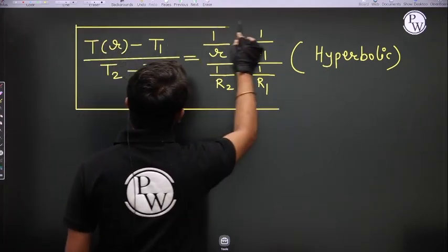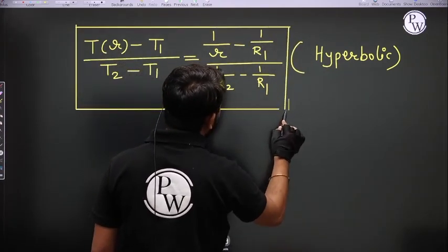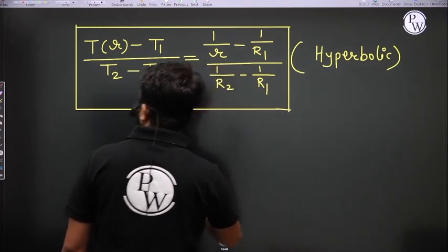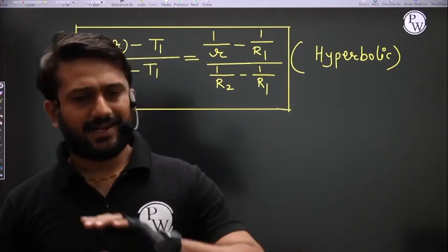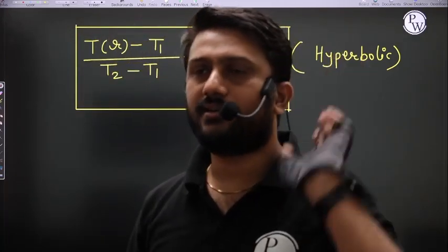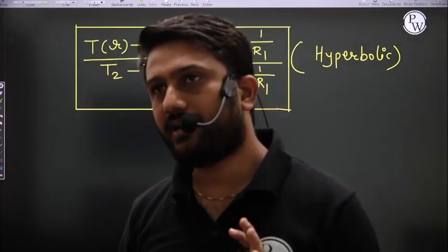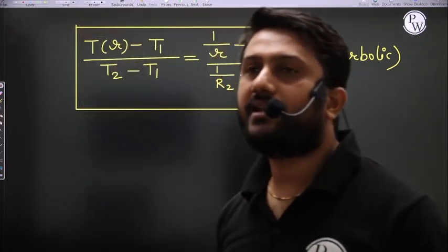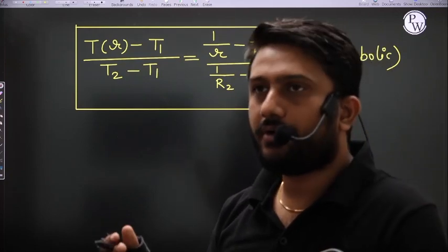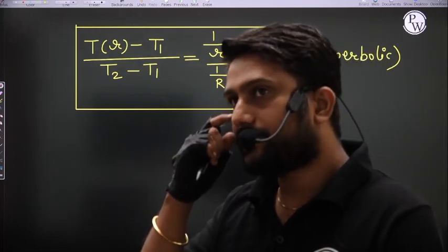Now the second objective is to find the rate of conduction heat transfer. To find it, consider a small elemental area like a hollow cylinder, and from that small elemental area the rate of conduction heat transfer is dq dot. Apply the Fourier law of heat conduction.